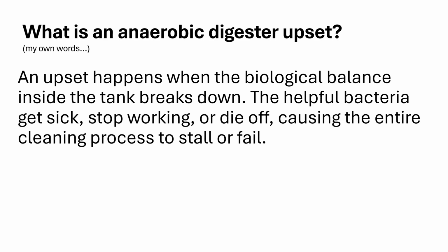We stressed our thermophilic bacteria out too much. They died off, or they got sick, or they just said, you know what, I'm going to take some time off to recover. They're going to take 24 hours off. They're going to call in sick. But we still got wastewater. We still got sewage coming in. We've got to treat it. So that's why a digester upset can cause us so many problems.